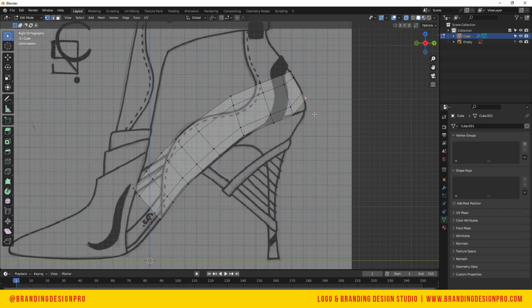like this. And we're gonna just select the vertices or the vertex. The way you can do that is by hitting 1. You can alternate between 1, 2, and 3 to select vertices, edges, and the actual polygon shapes, faces I mean. Alright, so let's just work on the shape. We're gonna hit Control R to add an edge loop there.